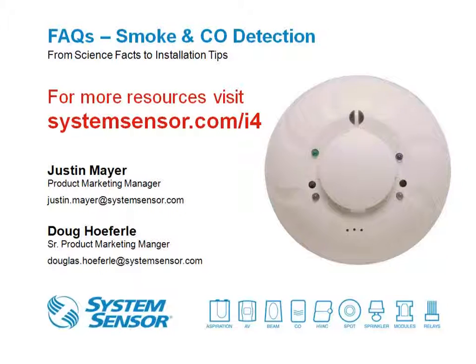A question here, guys. Maybe this one's for Doug because it's I-4 related. How many zones per I-4 module? I'm thinking they're asking how many zones on the panel the I-4 module requires. It requires a minimum of 2 zones on the panel, a smoke zone and a CO zone. And then, like I mentioned before, you can set the dip switch to report smoke maintenance to a separate maintenance zone as well.